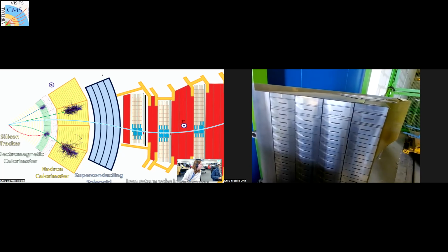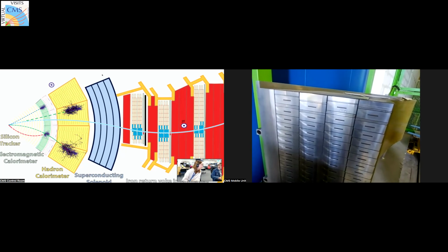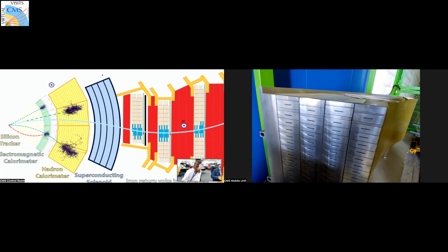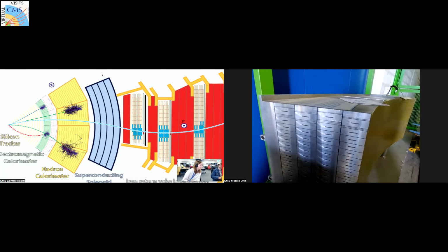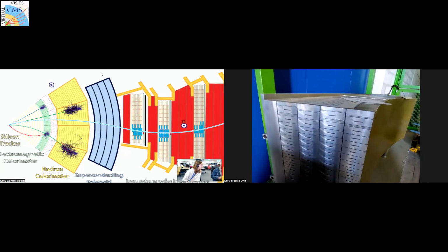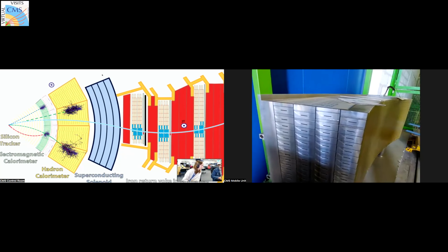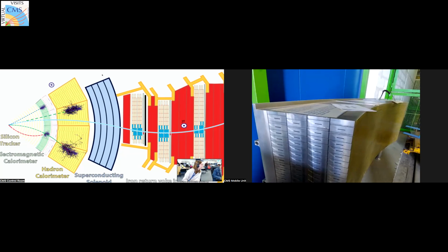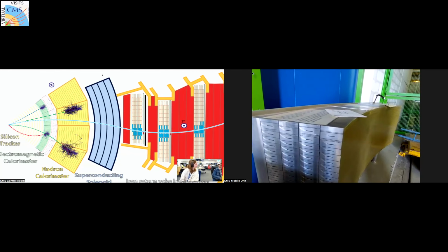At superconductive temperatures, when the niobium titanium starts to superconduct, that is with really zero resistivity, everything else that has a non-zero resistivity becomes an insulator. But once we lose the superconductivity, the aluminium turns on, it increases the cross-section, therefore decreases the Joule heat that results from this enormous current, and that gives us a little bit of time to dissipate that energy that is stored in the magnet, 2.2 gigajoules in case of CMS. We bring it up to the surface and dissipate it on a resistive network.